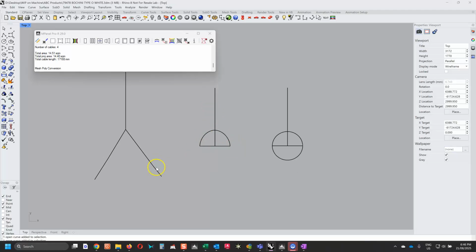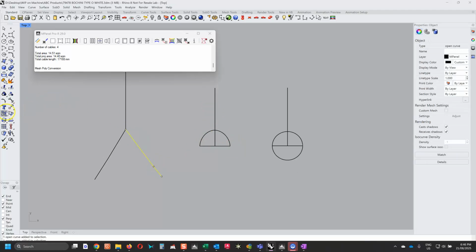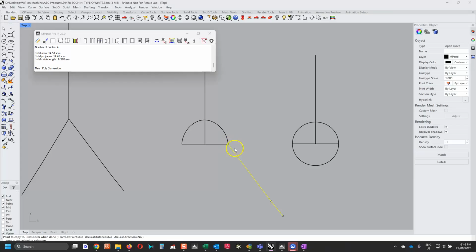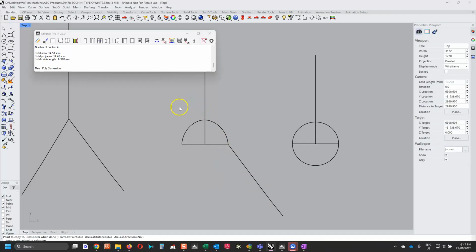When the cable length is calculated, it will be calculated from this point here to the other end. So exactly the same as before. If you're terminating the cable at this point, for example with a wire support thimble and a swage, you would need to add on from this point whatever additional length is required, or if you're fitting some sort of terminal device that is 100 millimeters long, then you would cut that off the cable length, subtract it off both ends.